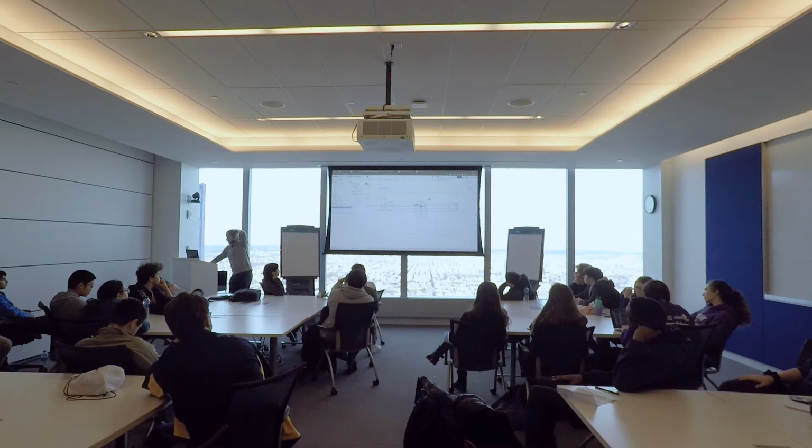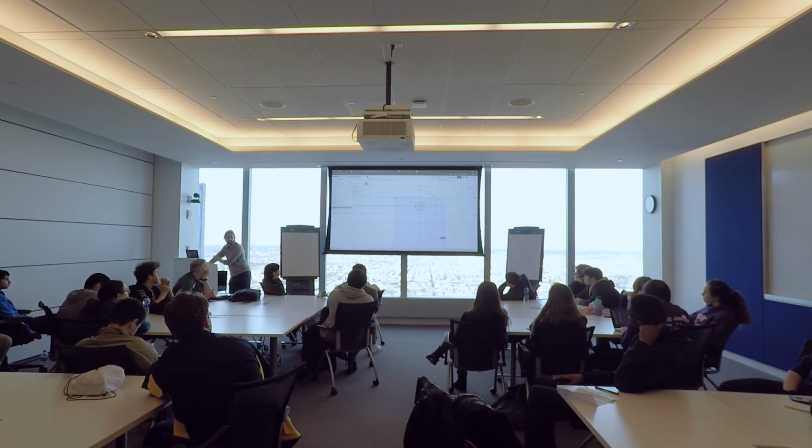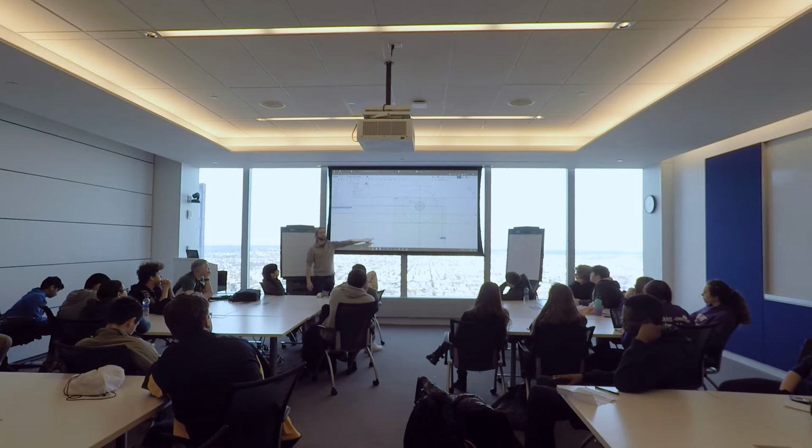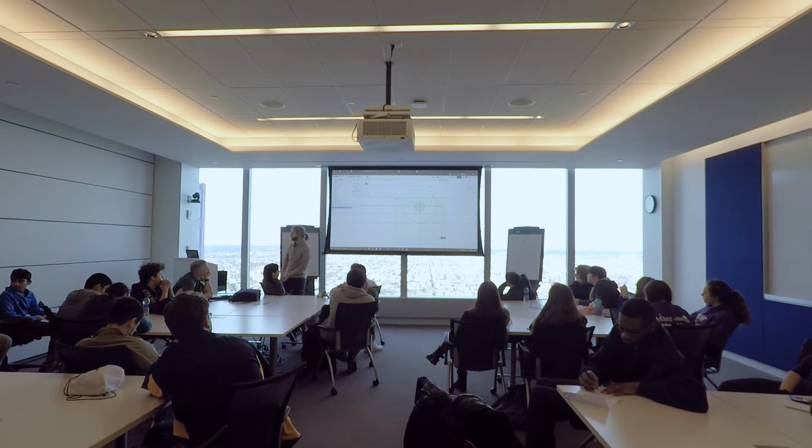I have the wheel defined by that wheel diameter, so that's a variable. If I went in here and changed that variable, it would automatically change the wheel diameter. And then my center drop, it's a little bit tricky to understand, but this is the center point of this line here. I have the wheel dropped 1/16 of an inch, which is half. It's my center drop divided by 2. So that's actually an equation. If I wanted to increase my center drop, all I need to do is change this variable up here, and it would automatically redo that calculation for me to set the center drop.